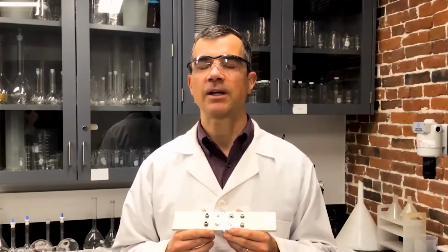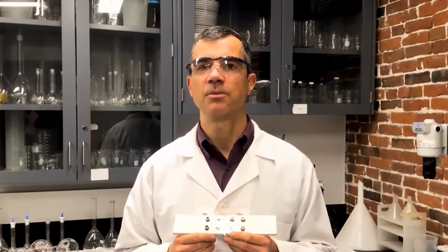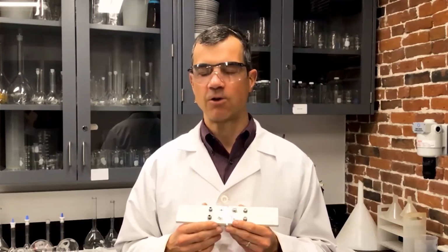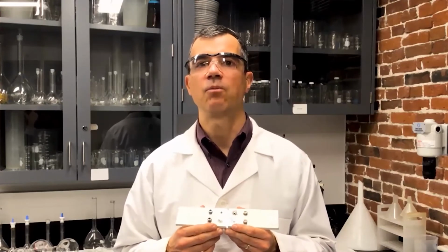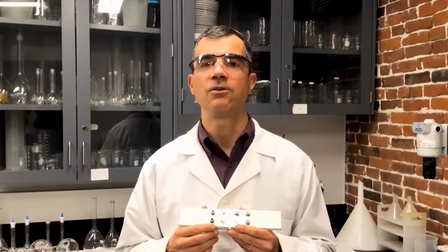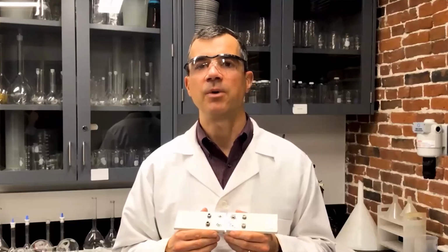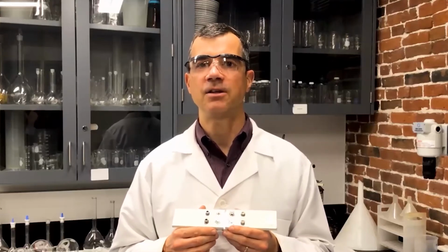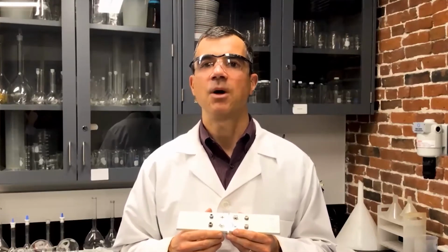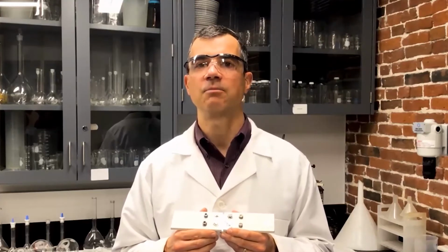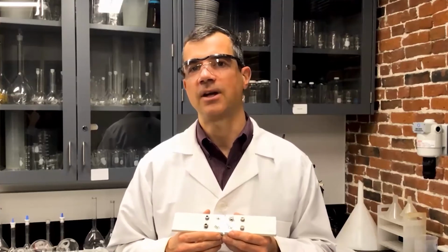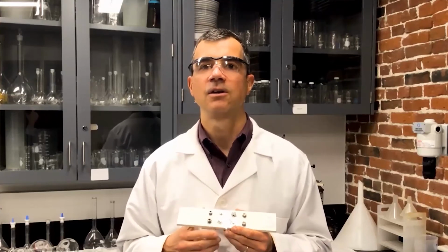But we recognize that there is a whole spectrum of different requirements. So we did the corrosion testing on this in the salt fog chamber, and we ran the test out all the way to the most demanding application. But we did have some alternatives that didn't make it all the way to the end, but we still found that they were viable solutions for some of the less mission critical applications on, say, a military aircraft.